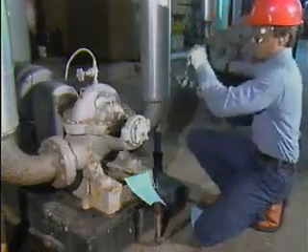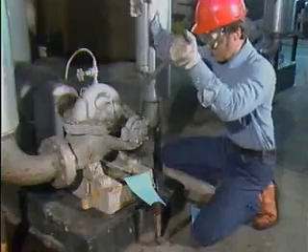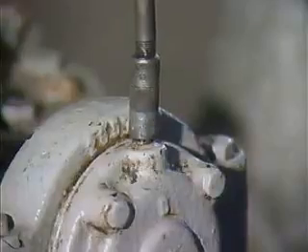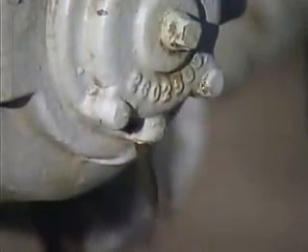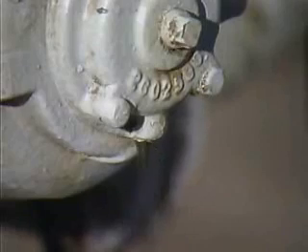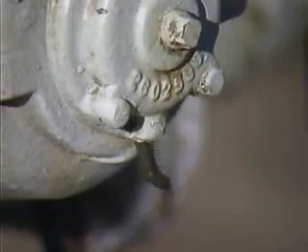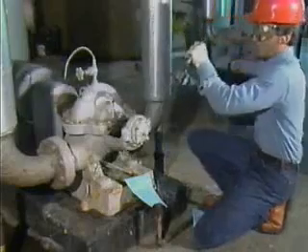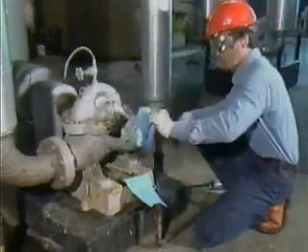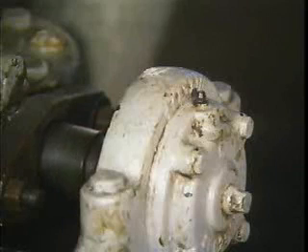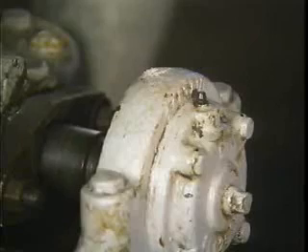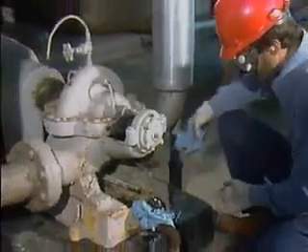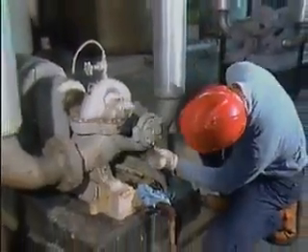Then connect the grease gun to the fitting and slowly add the specified amount of new grease while the machine is running. Don't overgrease the bearing. Typically, with a hand-operated grease gun, you should apply no more than 3 shots of grease at a time. Next, disconnect the grease gun from the fitting and wipe the fitting clean. Then, allow the machine to run for a few minutes with the drain plug still removed. As the machine operates, excess grease will be forced out of the drain hole. After a few minutes, wipe the drain plug clean and put it back in the drain hole.